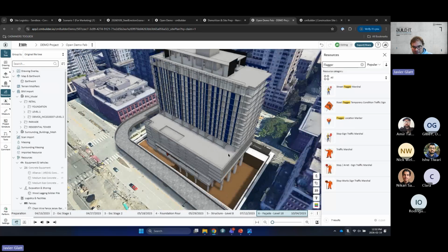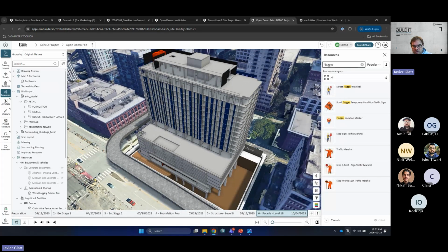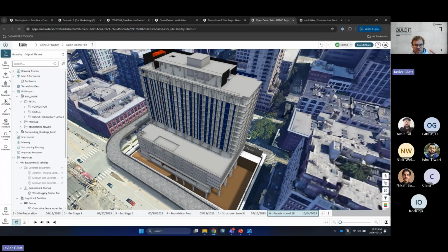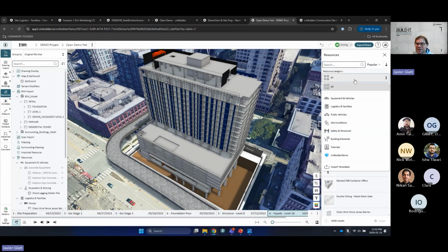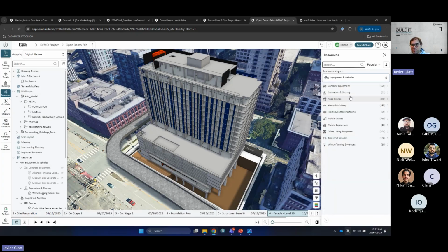And the next thing I want to do is talk about crane planning. So a job like this, where are you going to put the crane, where are you going to put the hoist relative to the crane. These are critical decisions that can really drive the productivity of the site. Typically, the construction companies we work with, there's only a handful of people in the entire company that are allowed to make decisions like this because they have a real impact. And planning these things better is a big need that we've seen in the market.